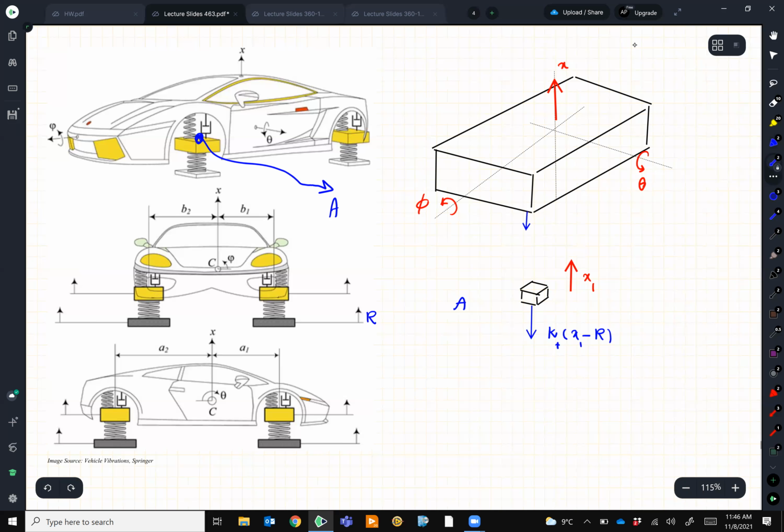The part where I've seen some people make mistakes is the force here and the reaction, of course, going there for the spring. And let's say the stiffness of this guy is K. So remember, this is for your tire, and they are different. Tire stiffness. And you can find the value on the internet or estimate them.